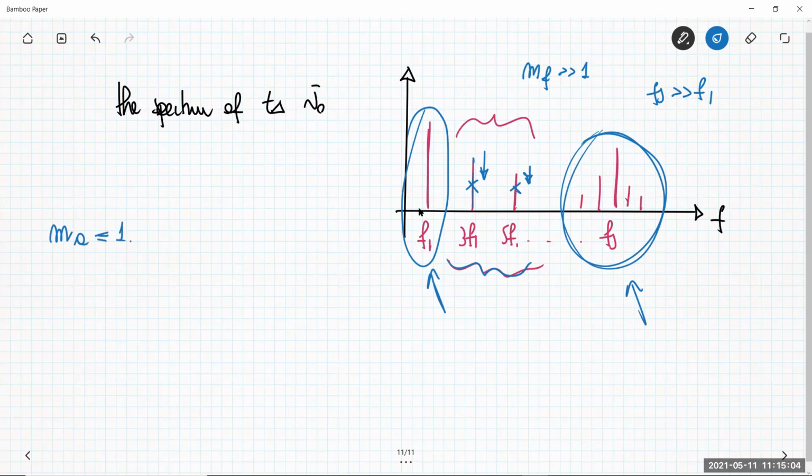So I have the control voltage, which now is a sine wave that has a peak-to-peak value. So the dynamic of the control voltage is always within the dynamic of the triangular waveform of the pulse width modulator. We are using this as a constraint. Then you are in the linear situation.